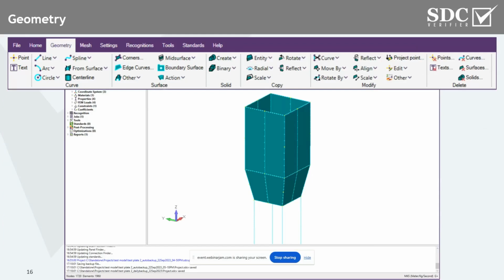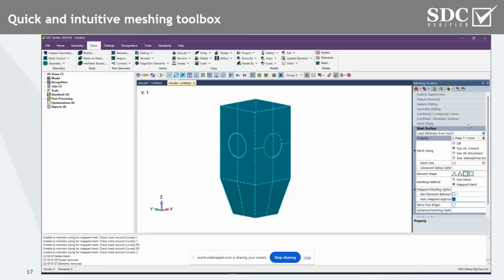But as you know, when it comes to FEA analysis, geometry is just the background for creating something that is directly taken into account by the analysis. So I'm talking about the mesh. Finite element software is not working on top of geometry or your CAD models, but it works with finite elements and the nodes. So basically you prepare geometry to create those finite elements. And then this is a pretty common pain point in terms of good mesh quality.